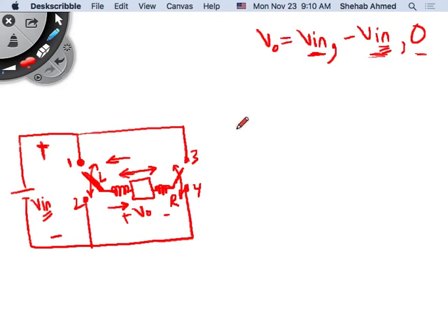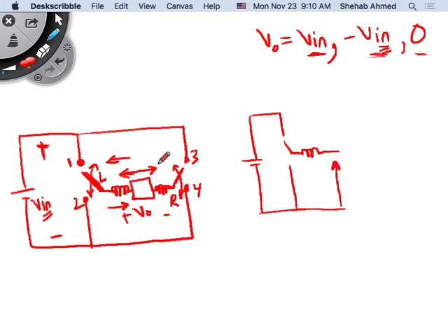Okay? I can think of this in a different way. That's something more like what we've been discussing in DC converters, right? So if I have this configuration, just looking at half of this thing, okay? This is operating with a duty cycle of D1, right? And this is my V input. We said that the average voltage I see here is always going to equal what? What's the voltage I will see here?